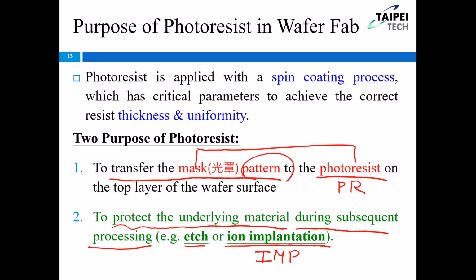We want to achieve an accurate photoresist thickness, and the uniformity is very important. For photolithography, you need to have a uniform thickness and, of course, an accurate thickness.